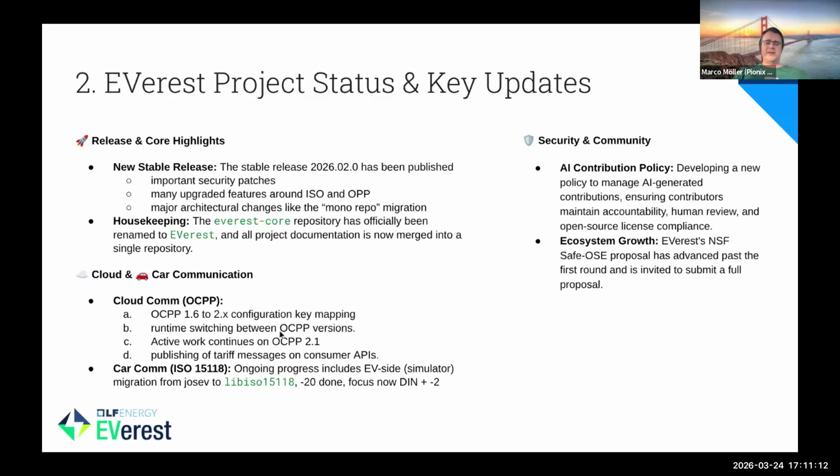The main short-term changes over the last four weeks are that OCPP 1.6 and 2.x now coexist more easily on the same EVerest instance, so it's not such a hard break switching between them. We are working quite actively on OCPP 2.1, not 2.0.1, which is more or less done, but 2.1, the very new version. On the ISO side, I think on -20 we've done a lot, but we're really actively working on a better car emulator, so you can run tightly integrated EVerest simulations.